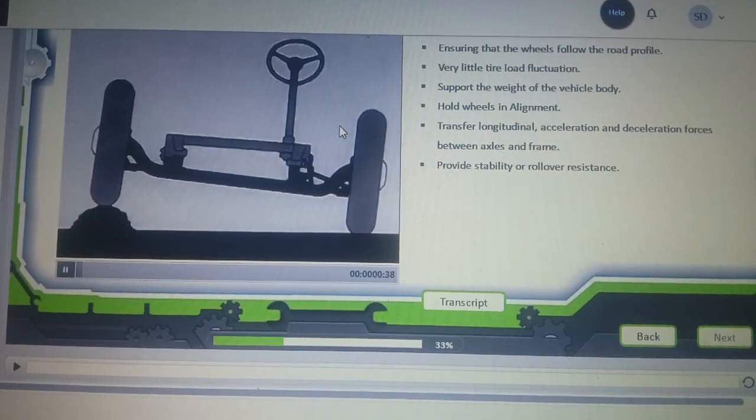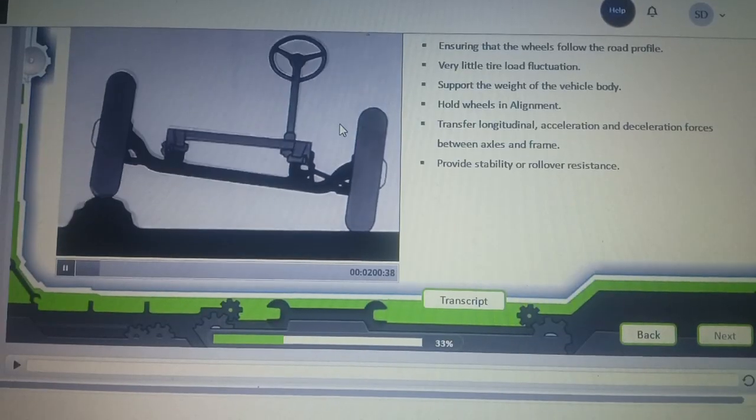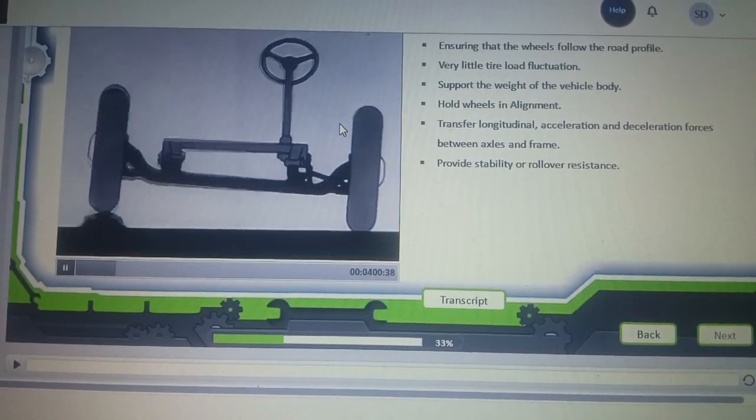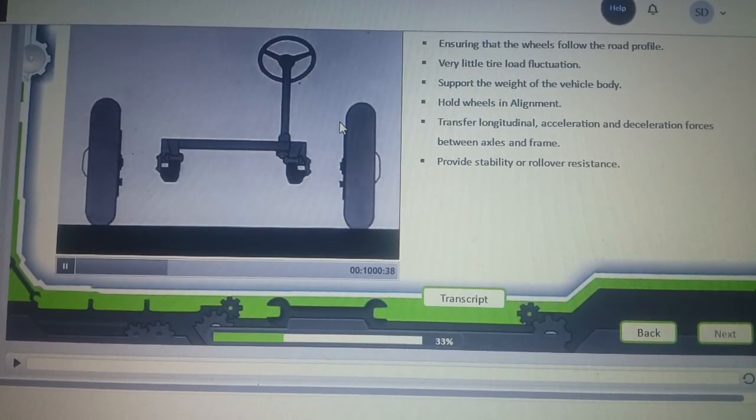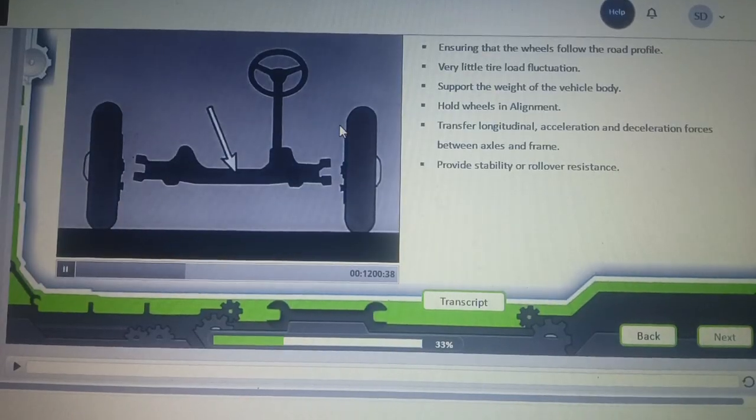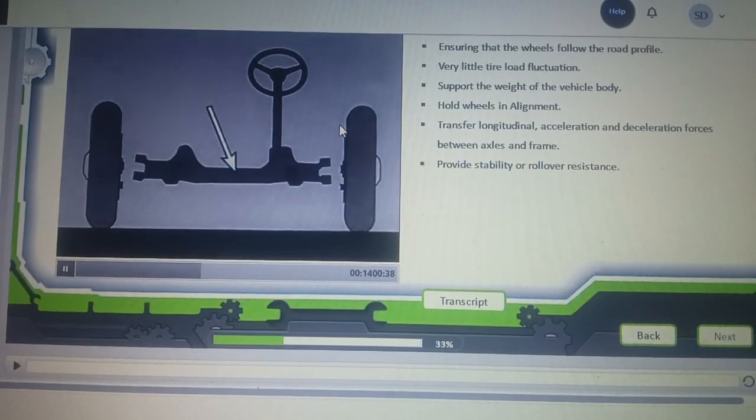The front springs should have only one job. They should not have to help in steering nor in supporting the axle as the old leaf springs did. So the axle has been put over instead of under the springs and made stronger than ever.